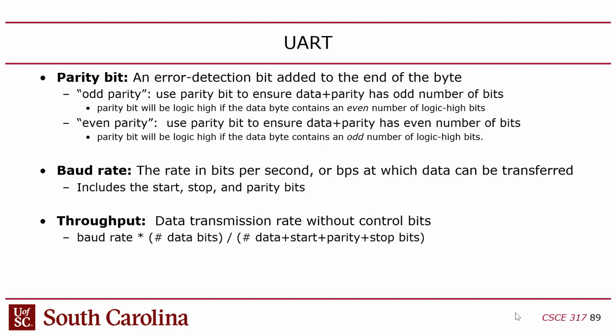So the first thing I have to do is not start reading the channel yet, because right after that falling edge, I have to give it 1 bit time, or 1 clock cycle, that I basically ignore, because that's the start bit. And then the next bit after that is going to be my first data bit, and I want to start reading at that point. I read that bit and then 7 more bits.